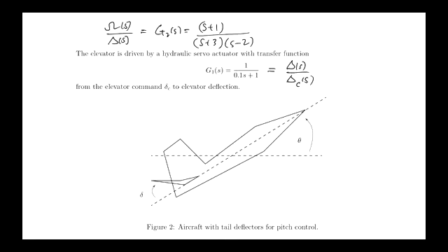All right, and because the centre of gravity is behind the axis, the behaviour of the aircraft is actually unstable. If you don't do anything, it'll just flip up, right? Because the weight here pulls it around and it flips up.